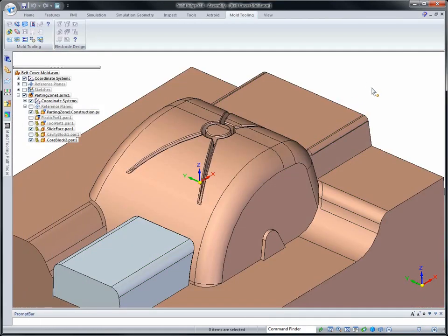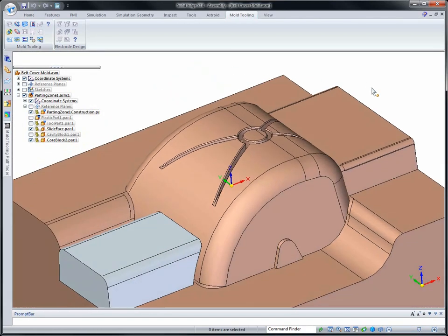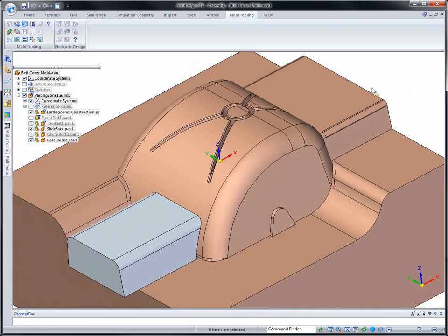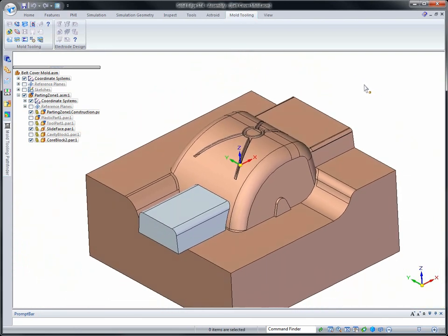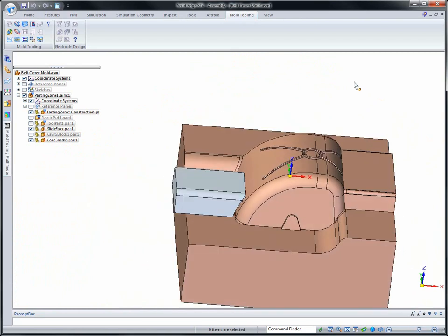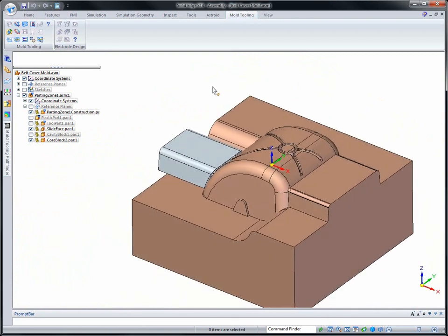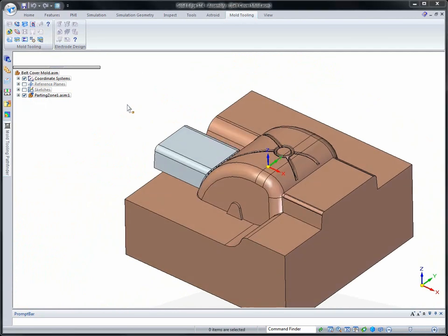Okay, so you have a nice smooth surface. You can see the inserted area where we got rid of that U shape going out the entire part. We could put an insert in there to create that, which again would be much more machinable. Step then is to define this as a 4-cavity mold. So what we want to do is pattern our core cavity set.